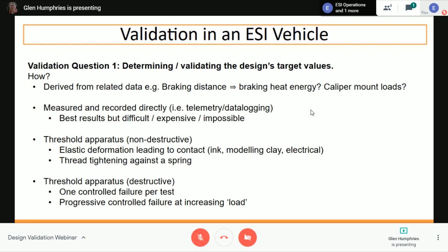So for example, what can we think of here? If you're running an independent 3-link rear, so you've got the main swing arm coming back from the chassis to the wheel, and then 2 parallel, or mostly parallel links going sideways. And those 2 links are purely tension compression. I'd say an example there, if you could replace one of those tension compression links with something that's got a very stiff spring in it.